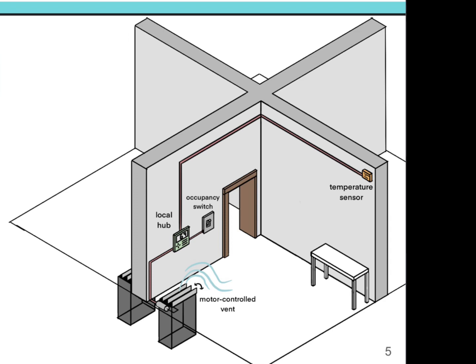And the occupancy sensors track whether the room is occupied or not and send it back to the main hub, where the user can enter in a desired temperature for both an occupied and an unoccupied room. And the thermostat in each room sends back the temperature of that room currently. And the central hub will take this information and whether the room is occupied or unoccupied and check to see if that temperature falls within the range.